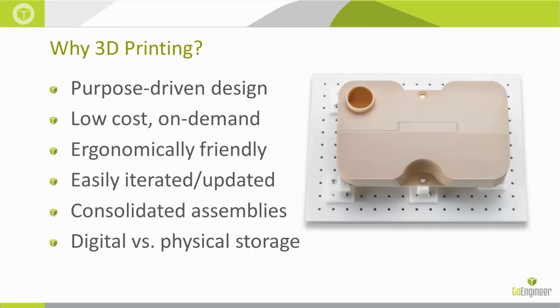Third thing that I came up with is 3D printing is very ergonomically friendly. This is a recurring theme that I've talked about for a while now. Going back to the unlimited design freedom, we can create shapes that are very swoopy, very organic, things that would be very comfortable for somebody to hold in their hands. And it doesn't cost us anything extra. Whereas with our traditional manufacturing methods, again, we're working with set shapes. We have flat stock, bar stock, square stock, plate. And then we have to figure out how to use those shapes and assemble them using the different types of bonding or adhesives or fasteners that we have available to us. With 3D printing, we can just design it exactly how we want it.